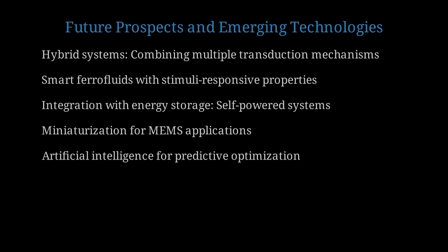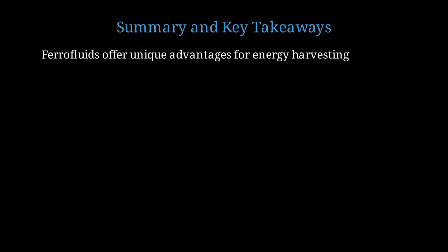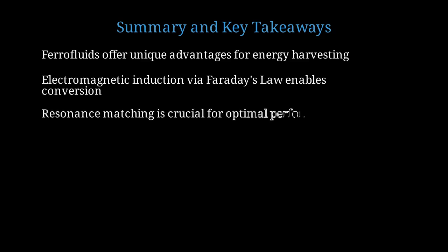Let me summarize the key concepts we've covered in this lecture. Ferrofluids offer unique advantages, including conformability, tunability, and reduced mechanical wear compared to solid magnet systems. The fundamental mechanism is electromagnetic induction governed by Faraday's law, converting mechanical oscillations into electrical energy. Resonance matching between excitation frequency and system natural frequency is crucial for achieving optimal power output.